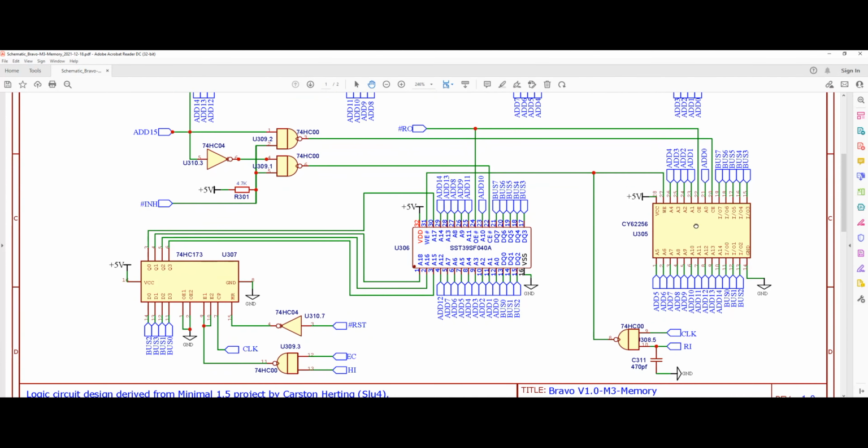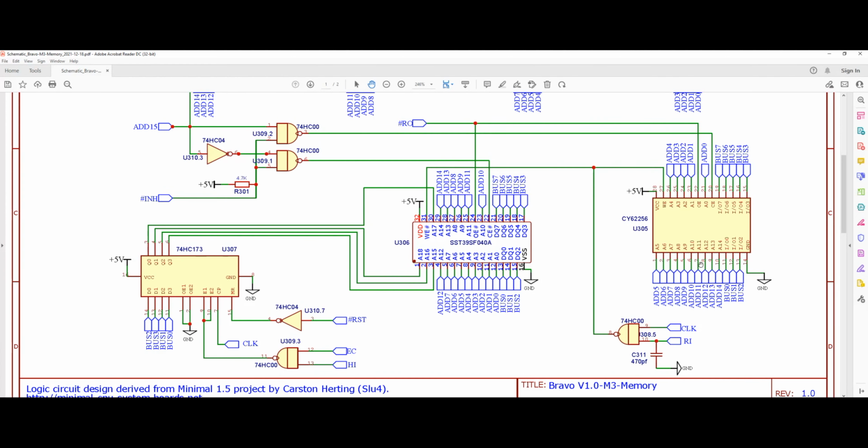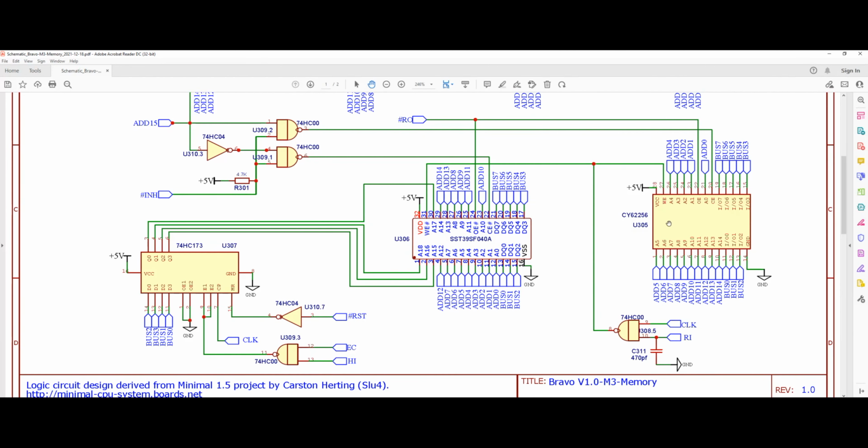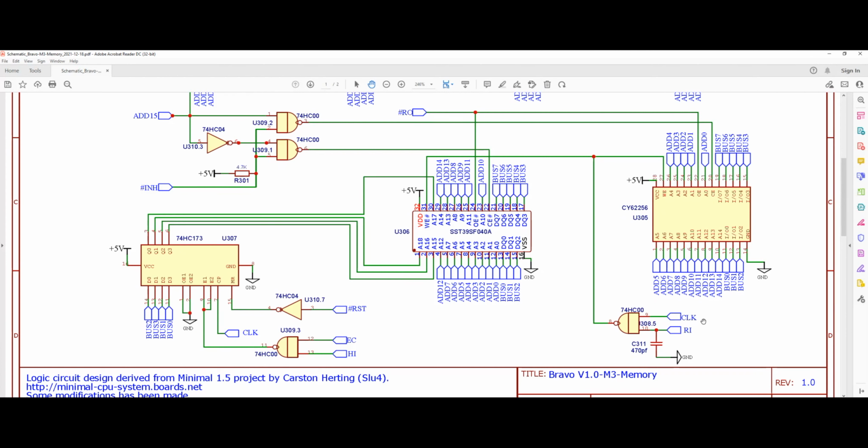Now let's first focus on the write enable line, which means that when we actually want to write to our memory from the bus, we are going to bring that line, which is pin number 27 here, to low. That's an active low signal again. And as you can see here, we have actually a signal in order to do that, which is called RAM in signal. So let's see how that RAM in signal actually works.